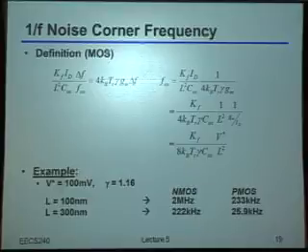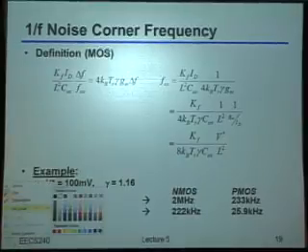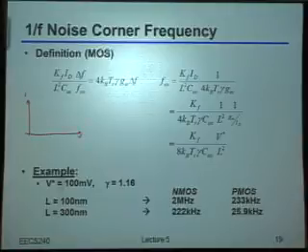So the other thing I'll just briefly mention in terms of flicker noise here is that typically speaking, rather than directly dealing with what that flicker noise current density is, people usually like to think of the so-called corner frequency. And so what they mean by that is just the following. So we said that in a MOSFET, we certainly have the thermal noise just due to the drain current itself. And if we do a plot of that noise current density versus frequency,